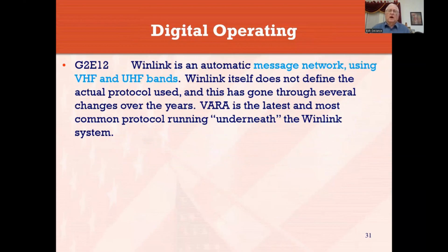WinLink, automatic message network using VHF and UHF, and take that with a grain of salt. There's a question to this effect, and the answer they're looking for is using VHF and UHF. However, we do use WinLink on the HF bands as well. Very popular on the HF bands, but for this particular question, this is kind of a gotcha. Watch out for VHF and UHF as the answer. WinLink itself does not define the actual protocol. WinLink is really a gateway system that processes the data, but it doesn't define what protocol you're going to actually use.